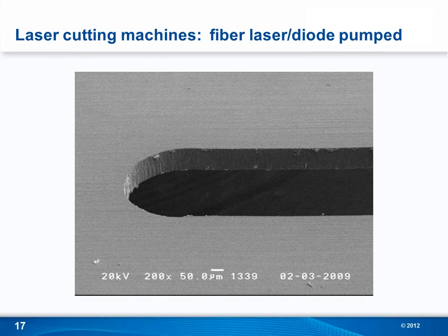When you compare a fiber laser system with the older lamp pumped lasers, the original ones were drawing 5 kilowatts or more of power to run the system. So it meant 3-phase 480 volts to power the system. The newer systems you can plug in the wall because the power consumption is less than a kilowatt.